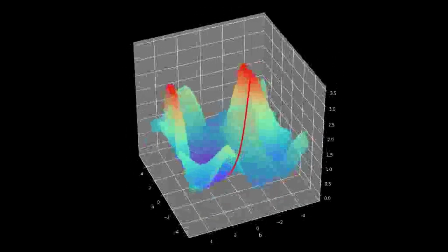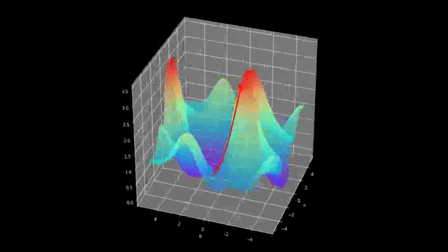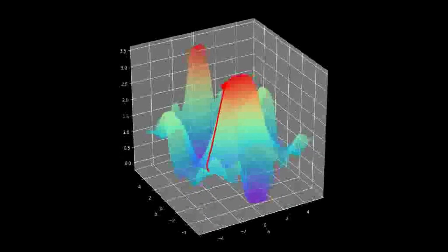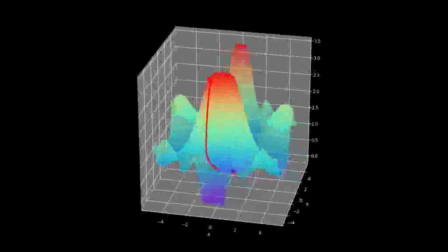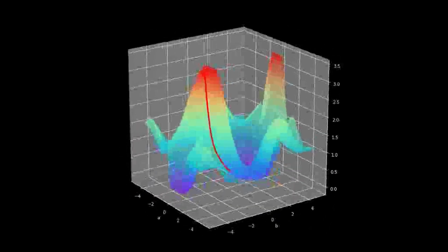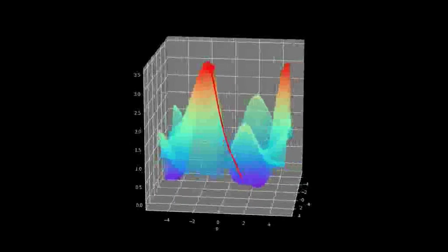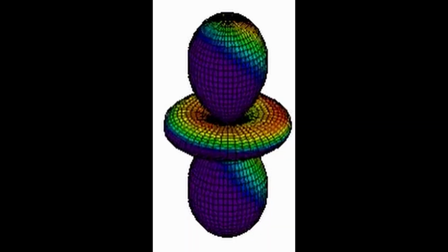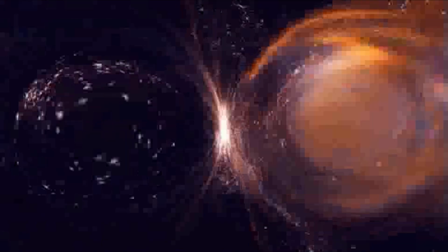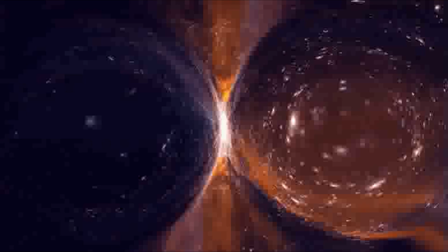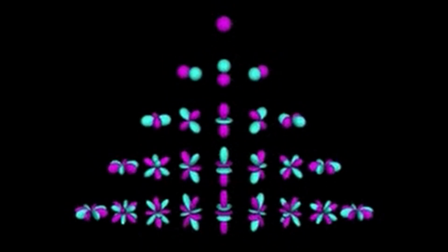2. Quantum tunneling and capacitance. In a typical setup, a small conducting island, like a quantum dot, is connected to leads via tunnel junctions. These junctions have a very small capacitance. When the island is small enough, the addition of a single electron significantly changes its electrostatic potential, creating an energy barrier that prevents further electrons from tunneling onto the island unless a certain threshold voltage is applied.